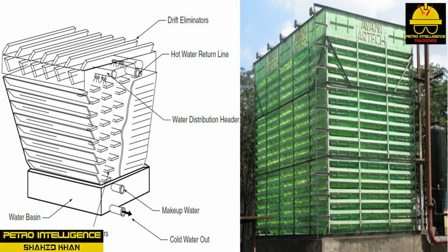Atmospheric cooling towers have a 30 to 55% efficiency rating for cooling water. Because this system does not require a fan, it is very cost-effective. However, its efficiency can fluctuate greatly because it depends on an uncontrollable factor, wind velocity. Heat transfer drops significantly with the loss of airflow.